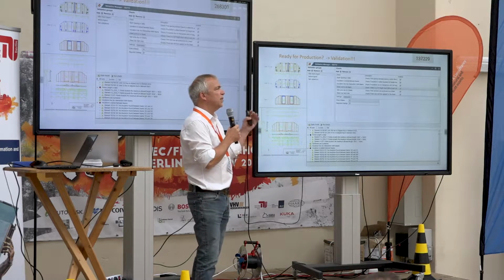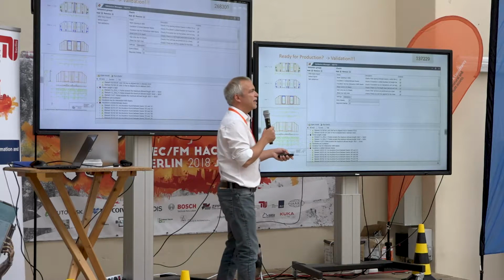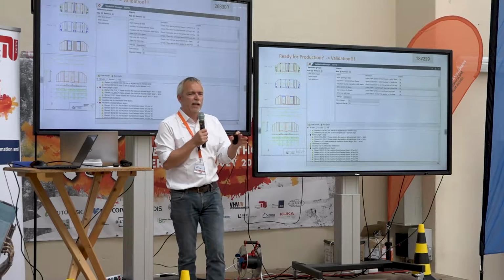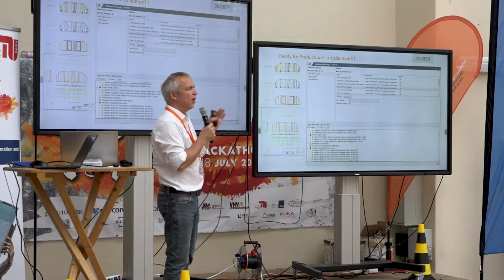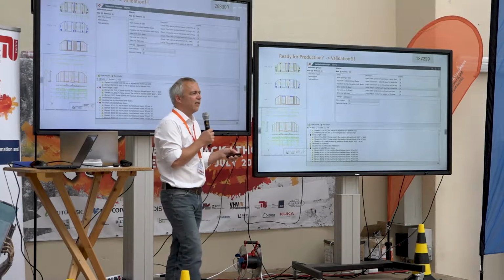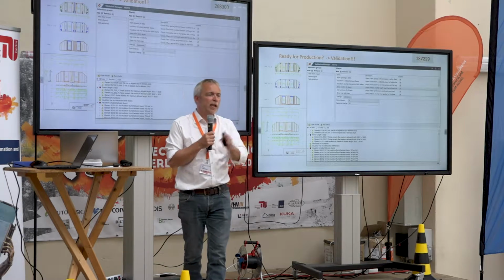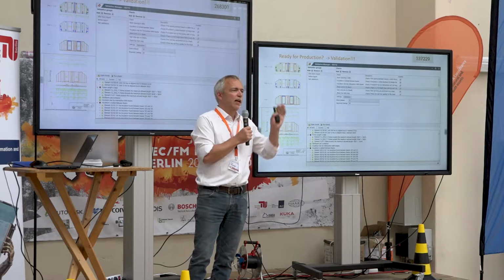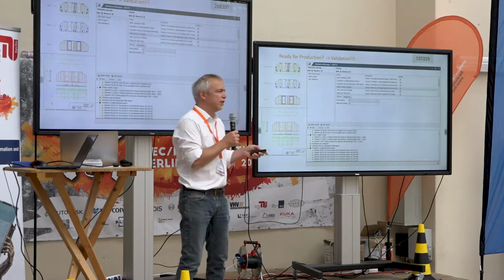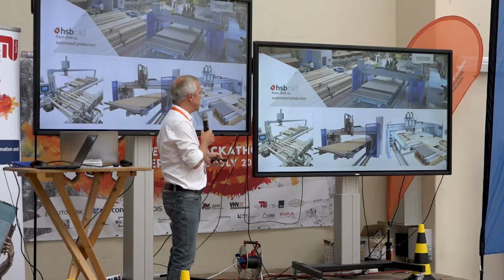So your automation in your design or in your detailing might need manual interaction. And after doing these manual interactions, you want to run your validation tests. Validations could be, is there a nail line on every edge of a sheeting board where there is a stud behind? Things like that. So these validations are obviously custom.